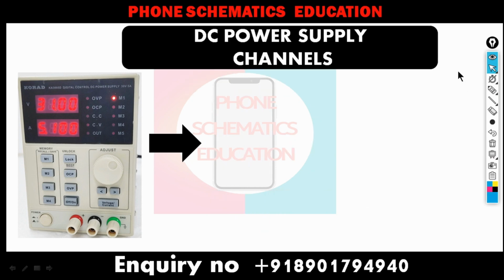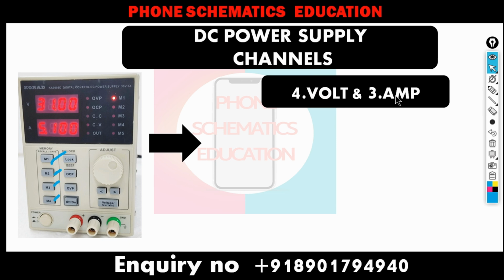Now next, DC power supply channels. These are the channels M1, M2, M3, M4. Right? There are four channels in this DC power supply. I'm using this one. Whatever channel settings I'm applying in my DC, I will share with you. First, 4 volt 3 amp in M1. I'm using this one for turning on the phone. Whenever a phone comes to me, I test the diagnosis with this through a boot cable or BMC circuit, whatever I have.